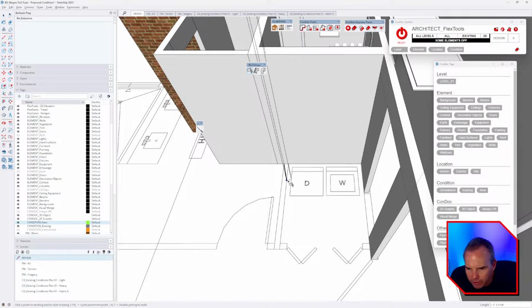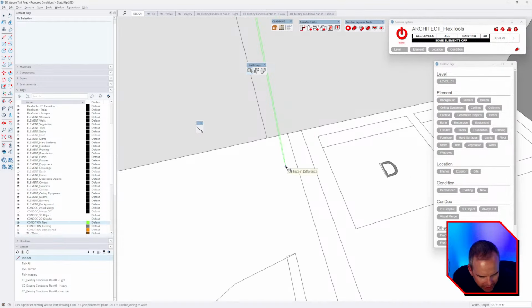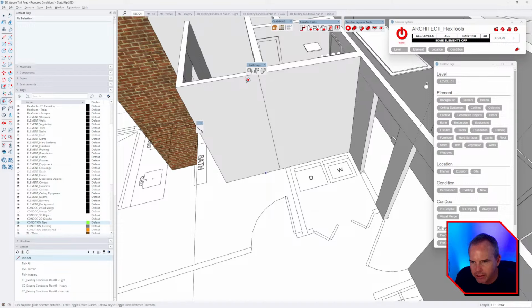So you can kind of draw a wall. If I look at the width and the height in the bottom right corner of my screen, you can see 3.5, 9'6". Let me check my wall dimensions. What are we drawing? We're at 7'6". So let me hit that wall tool again, say 3.5, 7'6", enter. So now I'm drawing these walls like this. I mean, that's pretty sweet, right?